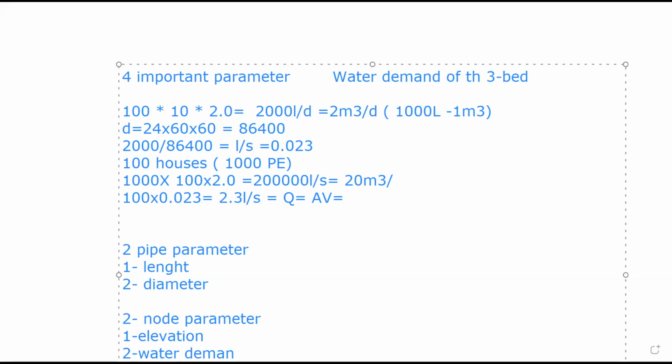Here on the taskbar, you could see frictional losses in pipes. Okay, 0.1, right? On the horizontal is the discharge. On the vertical is the slope. So with the slope and discharge, you can size the pipe. Any question?